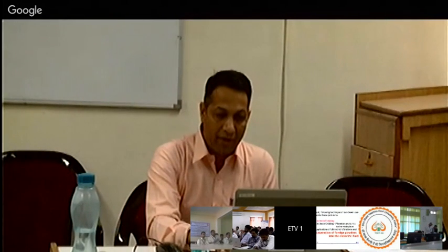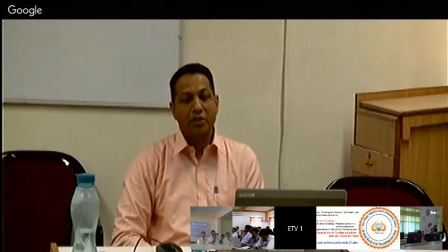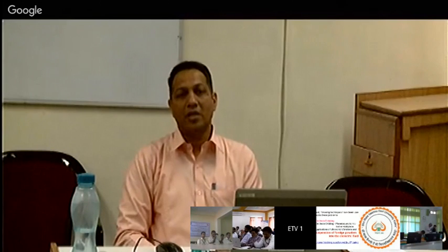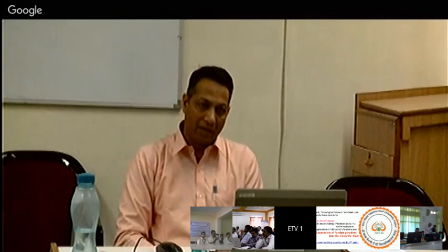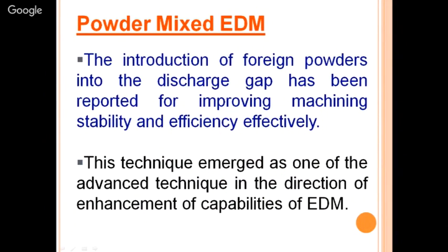So my dear friends, my research work is on this. The nano finishing is achieved by this fourth category, that is, by suspending some suitable material in powder form into the dielectric fluid of the EDM. So this EDM is called powder mixed EDM.